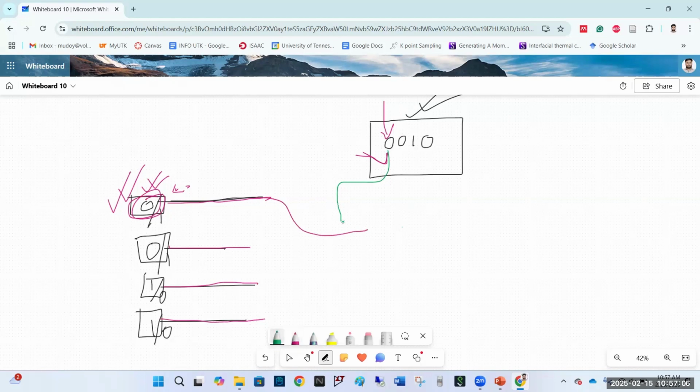So what should we do? We should match them, right? These two. The red one is from the user, and the green one is from the saved digit. So can I use an XNOR gate here, right? What does an XNOR gate do? It takes two inputs, and if there is a match, then it produces one, right? So that was the XNOR gate. If the inputs match, then the output is one.